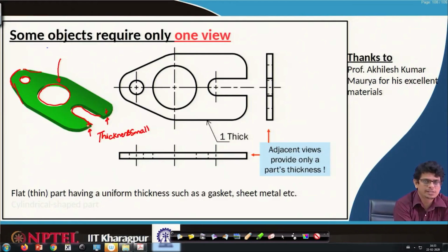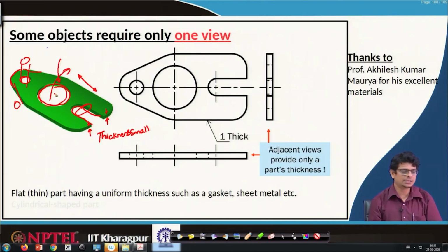To fix it on bolts using washers, we have this kind of slot also. So, perhaps one bolt can be inserted and tightened. This is the inlet pipeline through which gas might be coming out, and here also we will have a washer to slightly fix it, so that this entire object can be moved slightly here and there to align with the geometry. Such kinds of objects exist in mechanical engineering. So, let us look at the various views of this gasket.